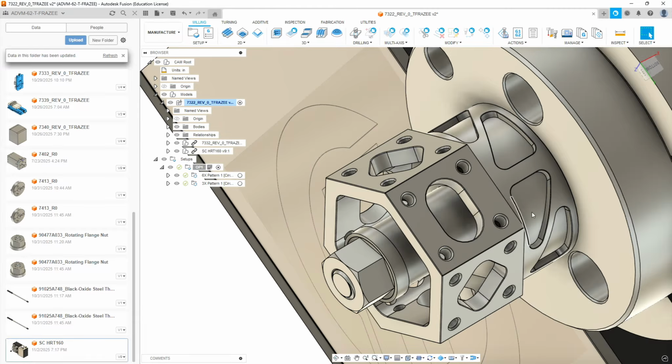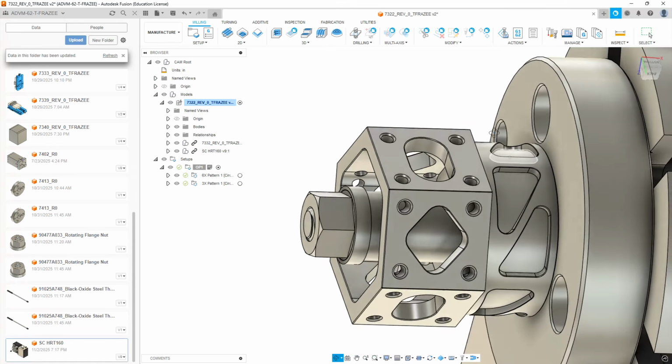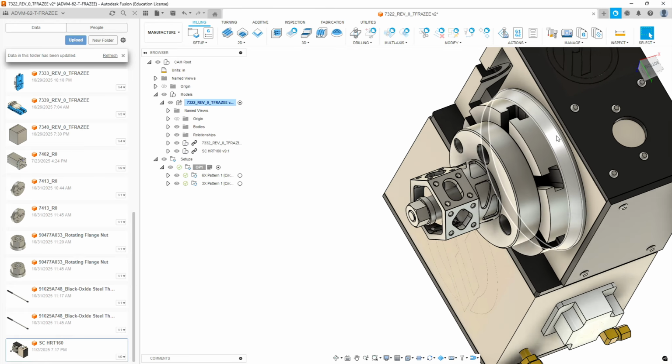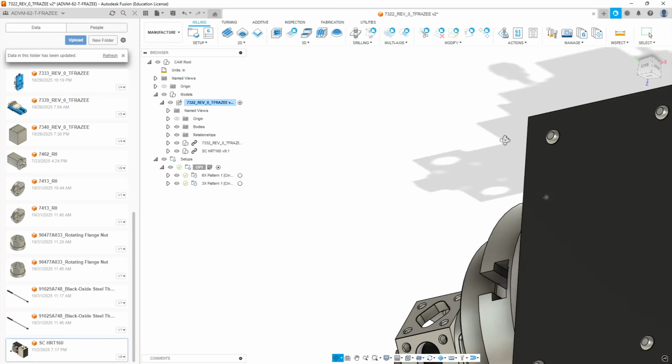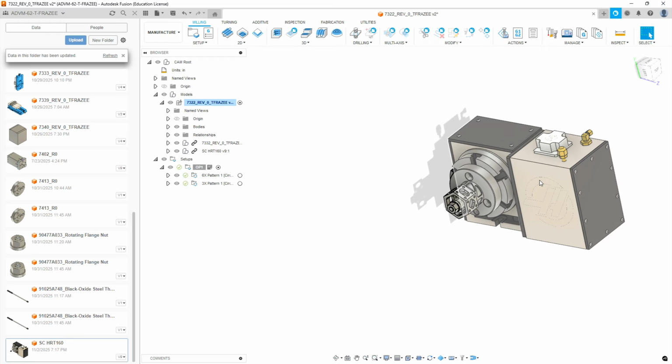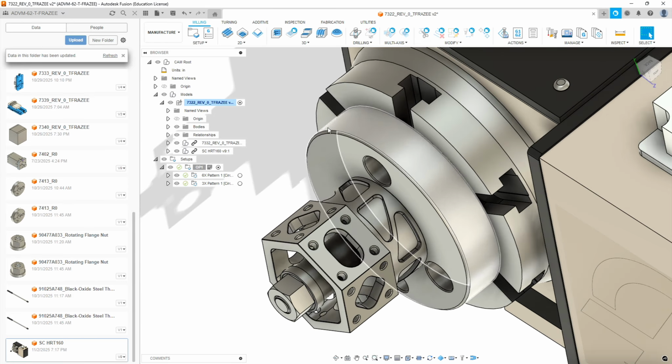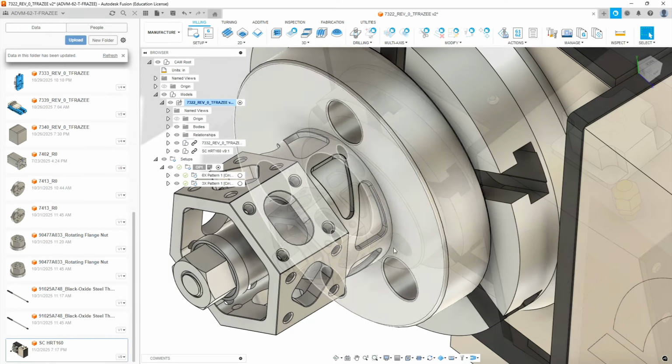Next, these things. These are wrapped pockets. As you see, the bottoms are cylindrical. So that is a command that you can use on pretty much any 2-axis command. Can be used on a wrap, but it only works in 4th axis. It does not work in 5-axis. We're going to go and we're going to machine these pockets.